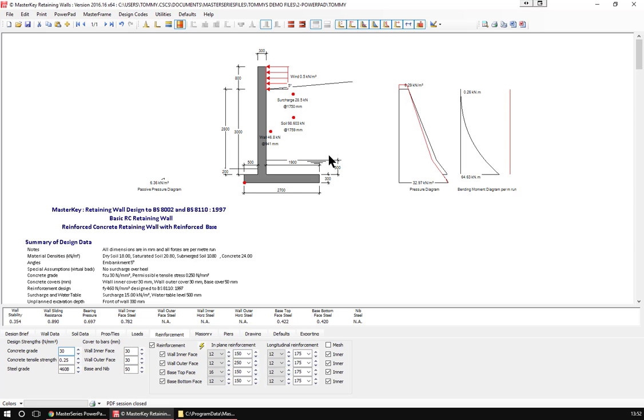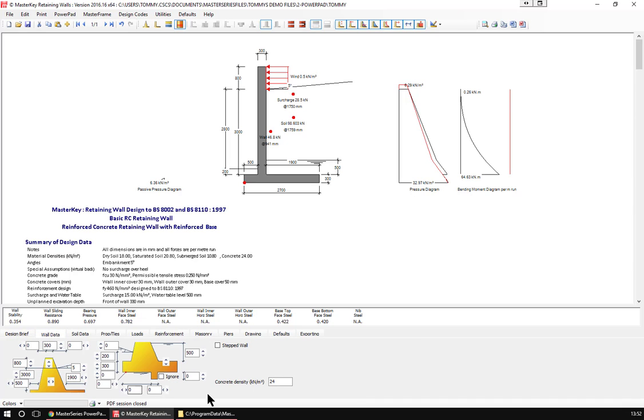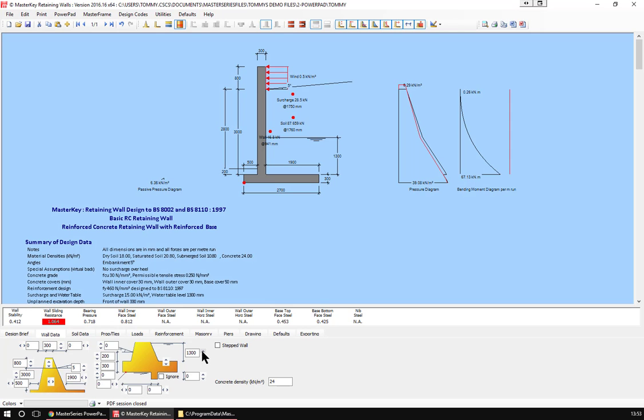That's really all I can say. Obviously the wall has a water table at 500 mil up. You're obviously pulling that down, which makes an improvement to the system. And we can see our capacity here changing due to the water table, and we see that starting to climb up. As we get higher, we're now beginning to get failure. In this case, we're getting failure due to sliding.